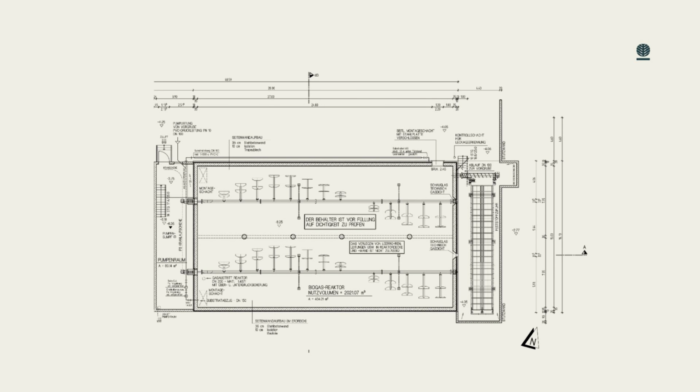As you can see on the right side, there is a screw conveyor, and all the substrate we have as a feedstock is brought into the digester as dry matter. So stones, metal parts, big wooden parts are not welcome. They block a pump or the screw. With this digester, we are able to feed the feedstock dry like it is, with 20, 30, 40% of dry matter content. And I can give you a small idea why we can do this.